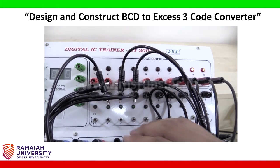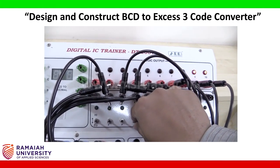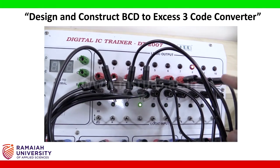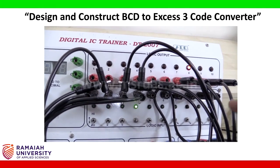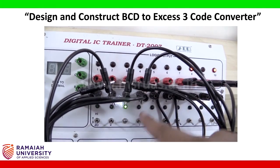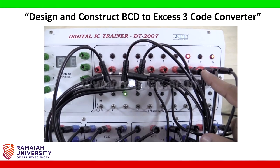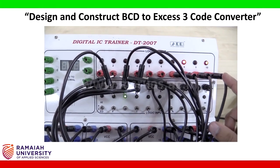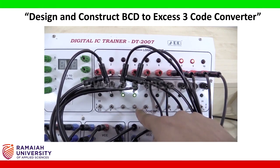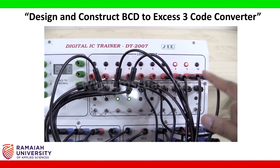For the next combination of the input, that is 0, 0, 0, 1, I will make the last input D high. So the output you can see is 0, 1, 0, 0. Similarly, for the next combination of the input, that is 0, 0, 1, 0, the third input I am making high, and you can see the output is 0, 1, 0, 1. So the next combination I will make 0, 0, 1, 1. You can see the output is 0, 1, 1, 0.